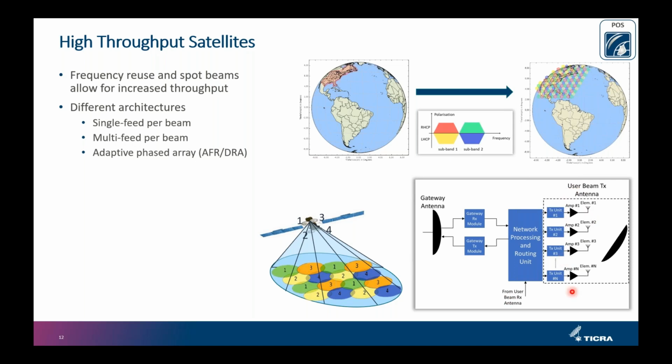So you have a lot of transmitting elements in your array, and each of these amplifiers, perhaps they can give you 5 watts, and you have 1,000 elements, so that's 5,000 watts in total, but maybe your satellite can only deliver 2,000 watts. So this means that even though your elements can go up to a certain level, you have to take into account that there are some higher level restrictions when you actually start doing the optimization of the array coefficients.